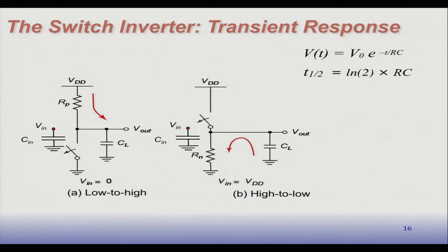If you do that and you look at the low to high transition, or the high to low transition, it's kind of just what I was talking about before. The model looks like this. The input to the transistor is the gate, and I said the gate acts like a capacitor, so if you want to affect a circuit, first you have to charge up the gate, looking into that circuit, in this case an inverter, so it'd be the sum of the capacitance of the P and the N-type transistor.